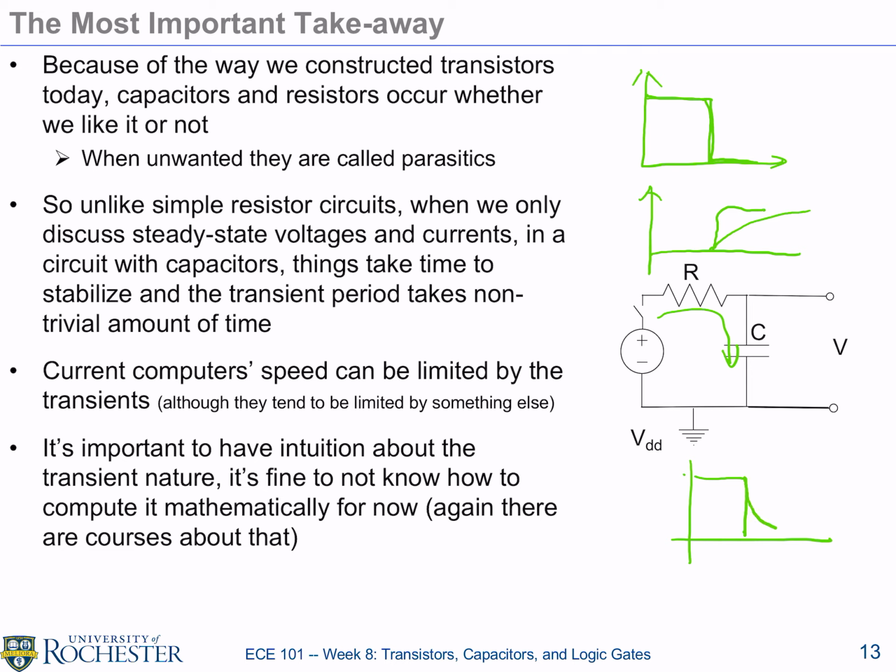It's going to go in an RC decay, an exponentially decaying function. Hence, your computer is not infinitely fast, even though they're plenty fast today, operating in gigahertz. That means all of these are much shorter than a clock cycle of a gigahertz or multi-gigahertz. The clock cycle is in the hundreds of picoseconds. So one of these transitions better be much smaller than hundreds of picoseconds. Otherwise, we won't get much done in one clock cycle.